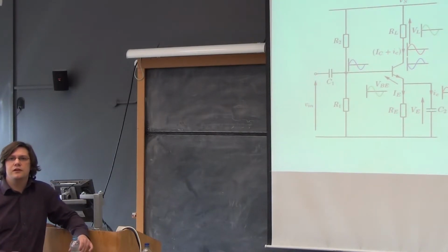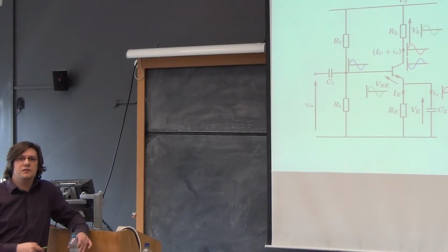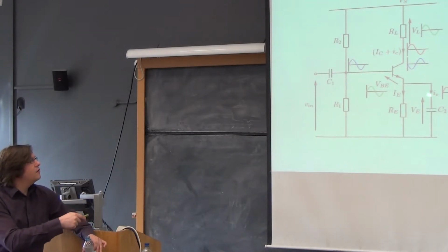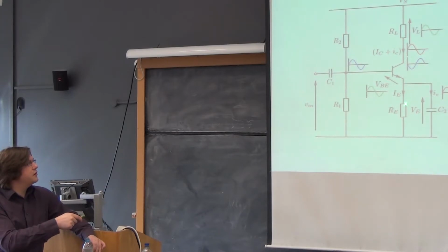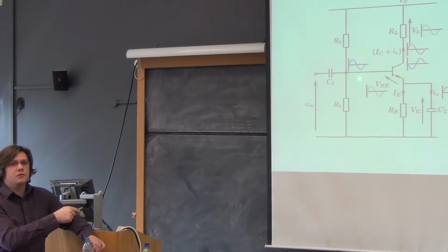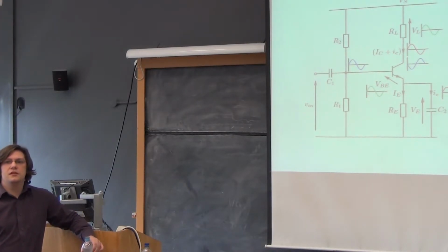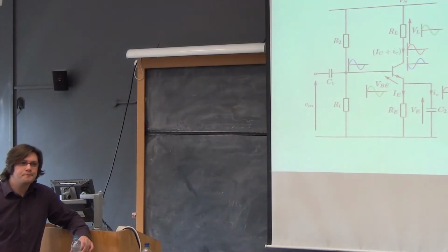It's the circuit that surrounds it that affects it. And it's the feeding back of the current flowing through the load, through the emitter resistor, producing a voltage across the emitter, subtracting from the base node voltage, which makes VB appear smaller. The transistor still has the same gain, it's just amplifying a smaller signal to start with.